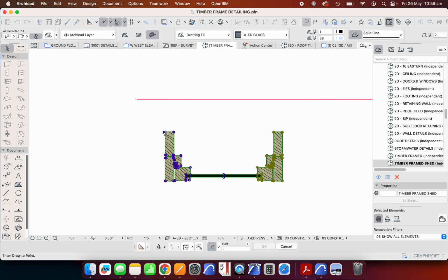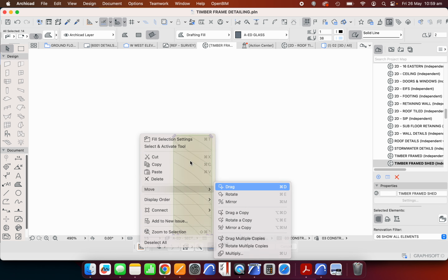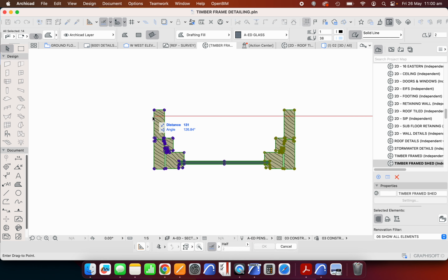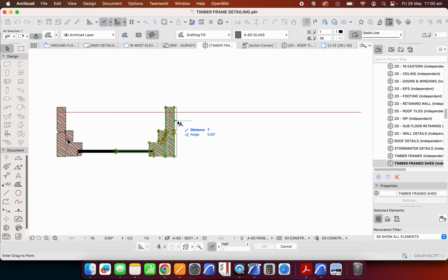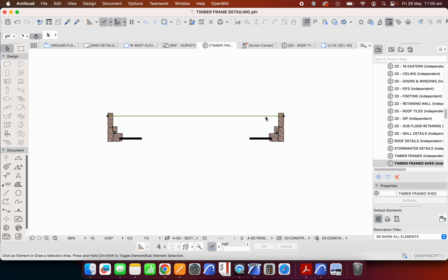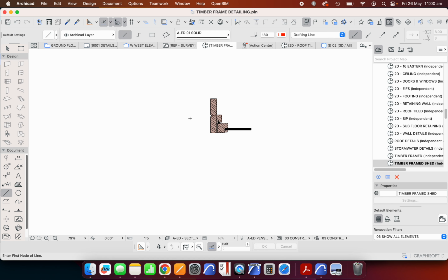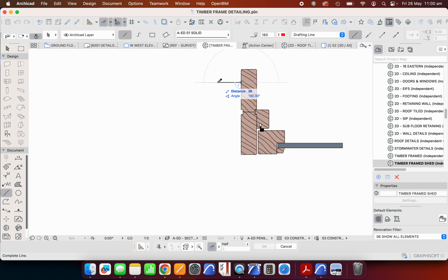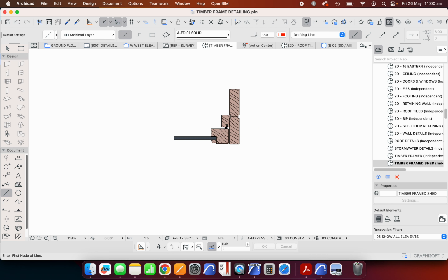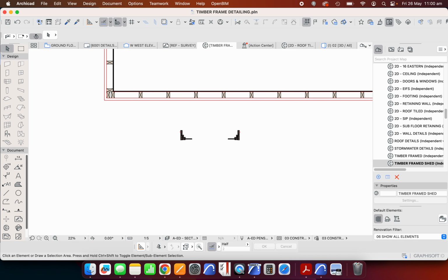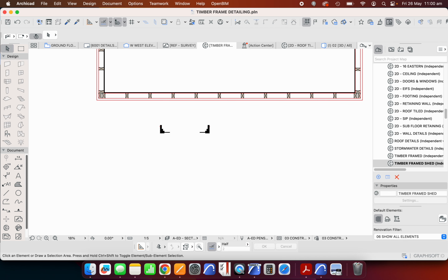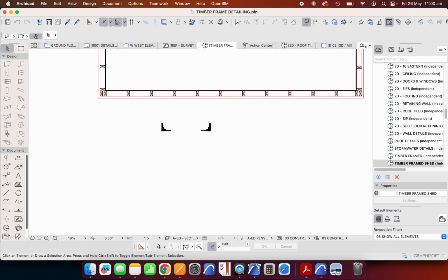And we measure that width, I have to do this zoomed in to get this correct, from the outside of the frame to the outside of the frame. Then we need an extra 10 mil tolerance on either side. So the frame, let's say this a different way. The stud spacing, the opening of the stud, needs to be 870. So we have an additional 10 mil on both sides. So when I go to place this into the wall, I'm going to need to adjust these studs in order to be able to do that.